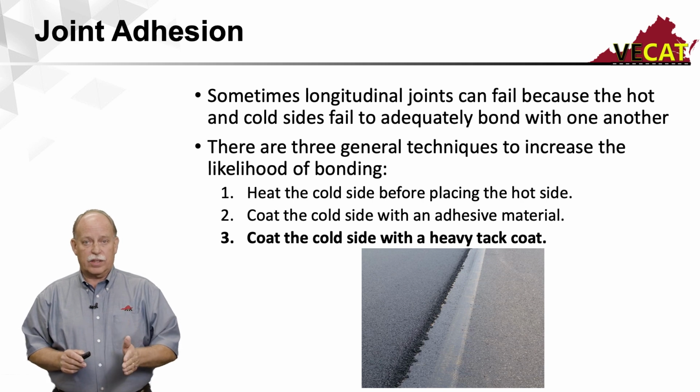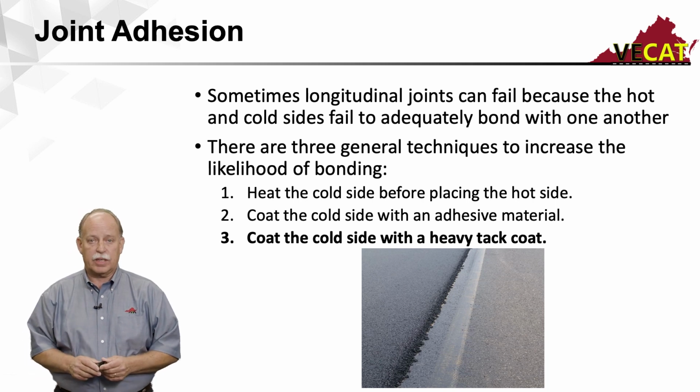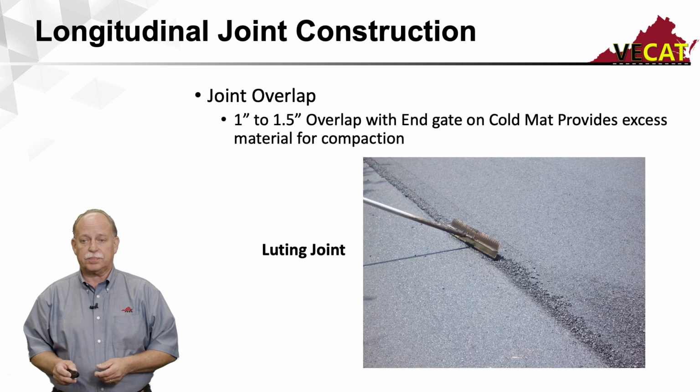That sealant that's placed there, the tack emulsion, will pull into that joint. It'll seal the joint against water, and because you put an extra heavy amount at the joint, it'll sometimes absorb into your pavement structure a little bit and provide a nice seal. As long as you get good compaction and you construct it correctly, they seem to perform very well.